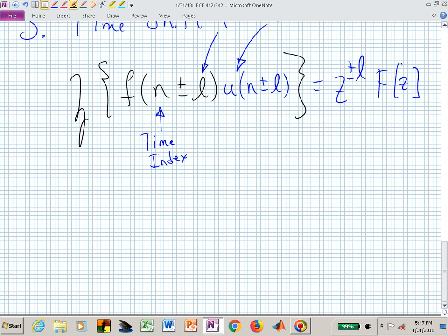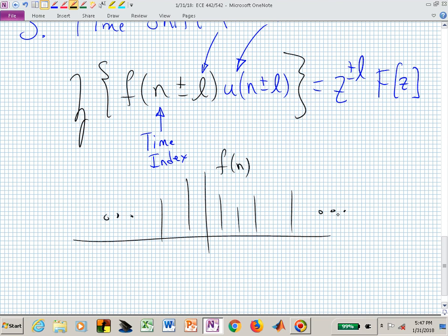So the question was, I'm paraphrasing, but going back to an earlier question, you can sort of view that unit step like you're cutting off half of your time waveform, your waveform f of n. Let's say this is now our f of n, which is doing this. And this unit step, let's say that L was equal to 2, then we would go over here, and this should be aligned, but I'm making it offset so that you can see the difference. Let's say this is minus 2. This thing is on now, and it's throwing away everything that was to the left of where that unit step kicked on. Here is now u of n minus 2. I don't know if that helps or not, but now it's saying, forget about what's to the left.